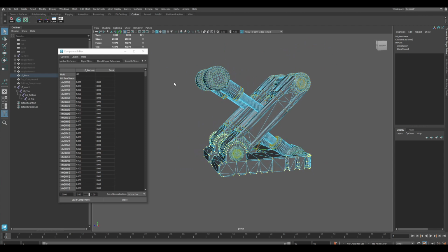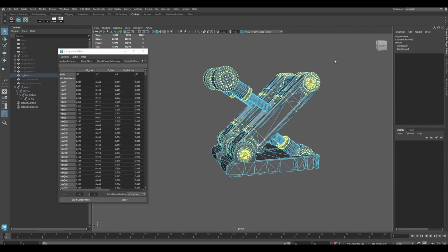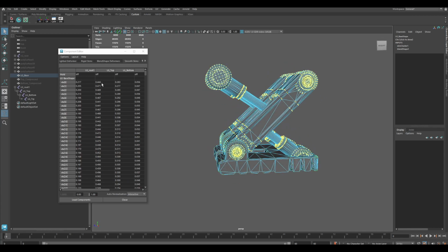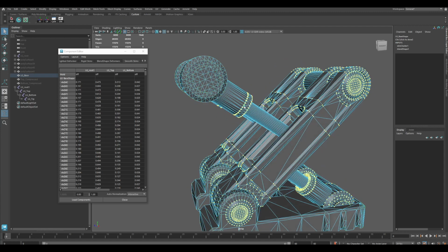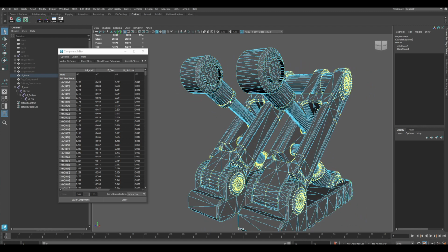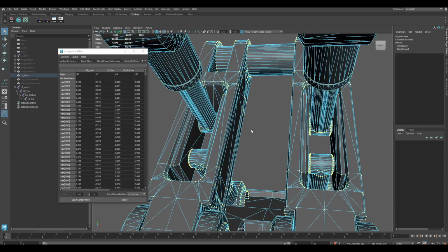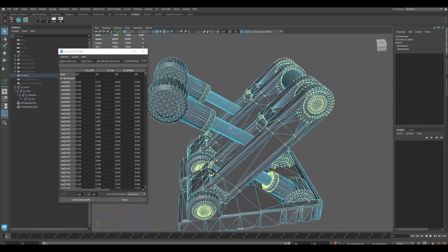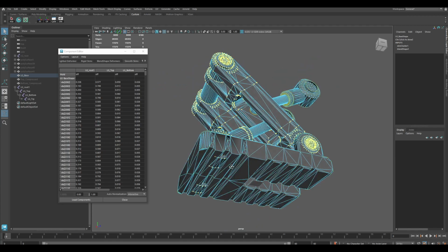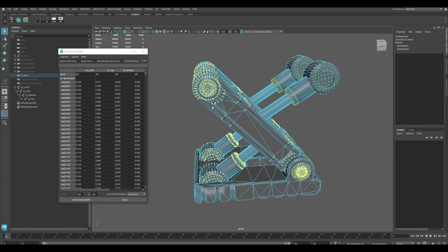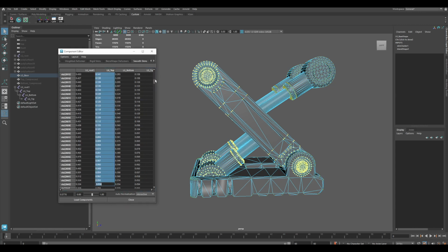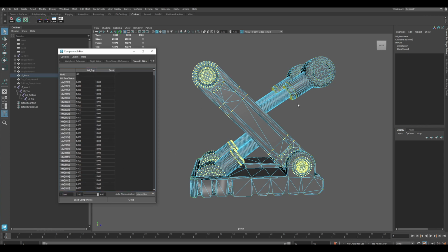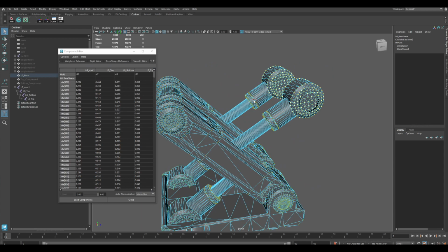Everything else, let's hide the bones. Everything else should be connected to the top bone except this top suspension, which will connect to the root bone. Deselect this top suspension. And both the bottom suspension and the top arm of the suspension will be moved with our top bone. So add 1 for all those vertices. And now for our top suspension.